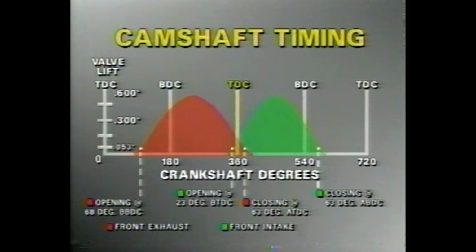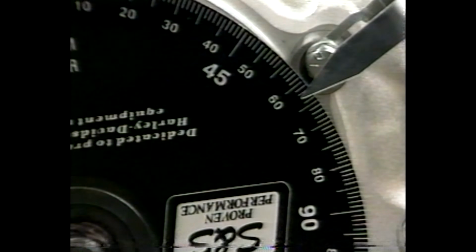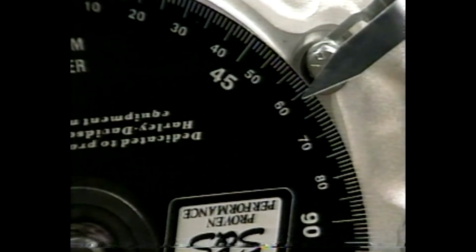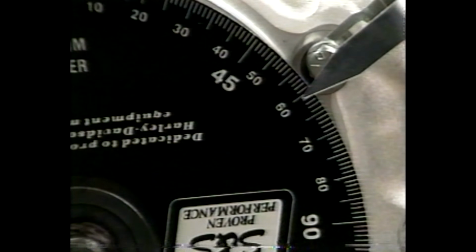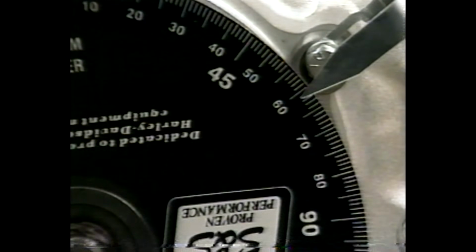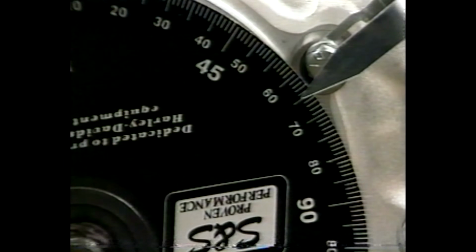In high-performance engines, where that extra 1/100th of a second makes all the difference between winning and losing, the cam timing in our engine must match exactly the camshaft manufacturer's recommended cam timing. In milder street engines, we usually allow a tolerance of 2 to 3 degrees in meeting the timing specifications of either cam. That is, our front intake valve could close anywhere between 61 degrees and 65 degrees after bottom dead center, and we would consider this valve timing to be acceptable.